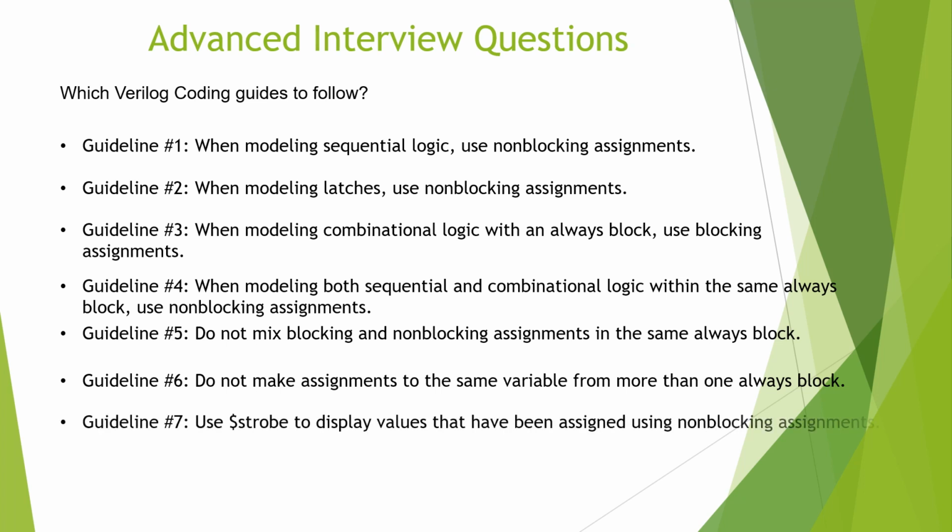Guideline number seven, use $strobe to display values that have been assigned using non-blocking assignments. And then the last guideline, number eight, is do not make assignments using zero delays. So friends, these are very critical guidelines which really help to minimize the bugs in your design and also bring your Verilog code as close as possible to the actual synthesized hardware behavior.